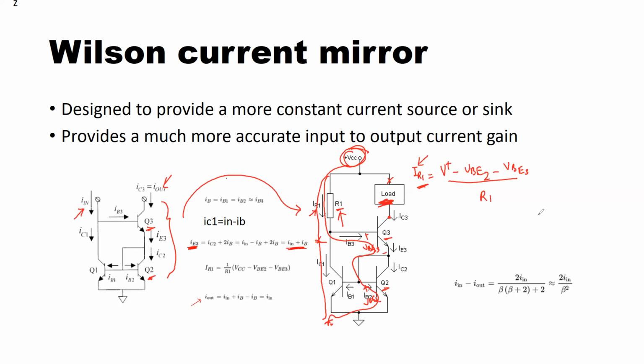Okay. So as a designer, you need to design a current reference or a current source independent of supply, that is the voltage, independent of the temperature, and independent of the process. So PVT, that's called process, voltage and temperature.